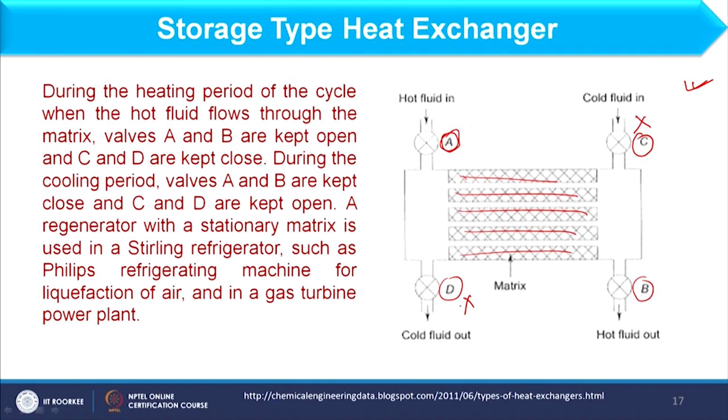So the hot fluid that is moving will enter, transfer its heat to this matrix and then exit from here. The second time, this will be open and this will be closed. So cold fluid will pass through this, take heat from the matrix and then exit from here. In this way, this matrix is used as a media to store the